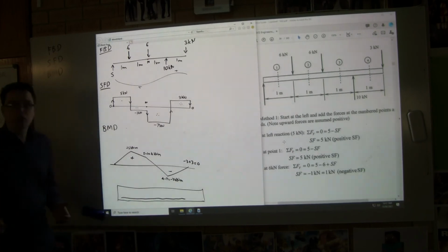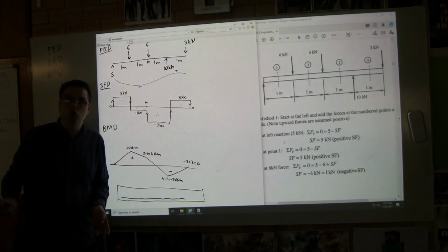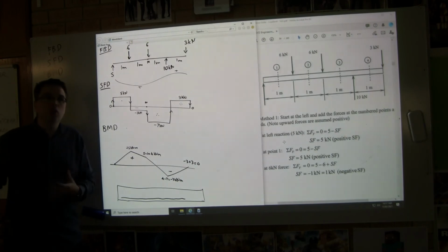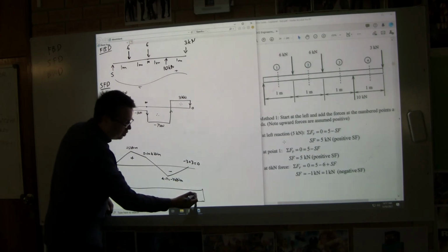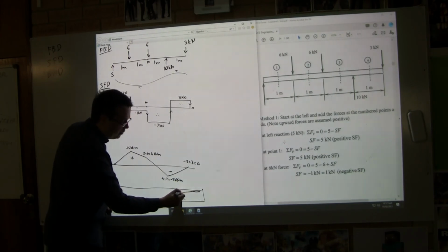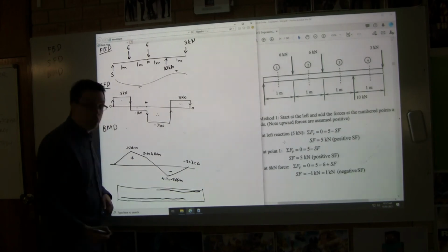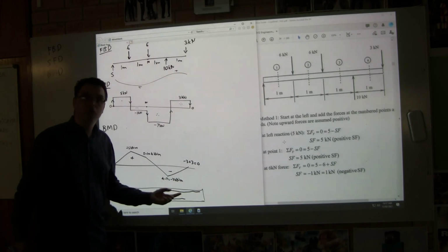But normally we don't have to put steel in the top. If we need to make a really strong beam, we can add extra steel to both top and bottom. But normally we don't have to put steel on the top unless the top is in tension, in which case we have to put some steel there. Yeah, we have to put some steel wherever it's in tension, because concrete is no good in tension. We need to put some steel there so that it can be strong in tension.